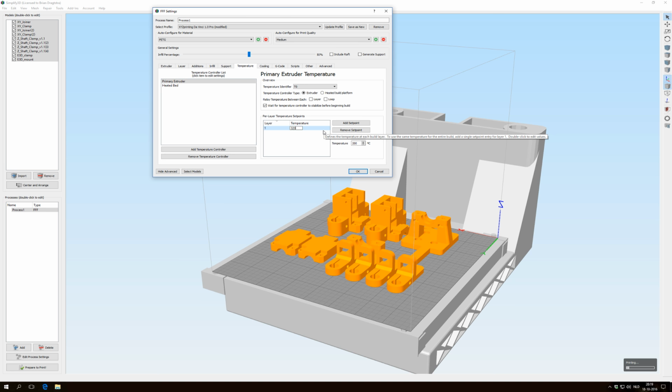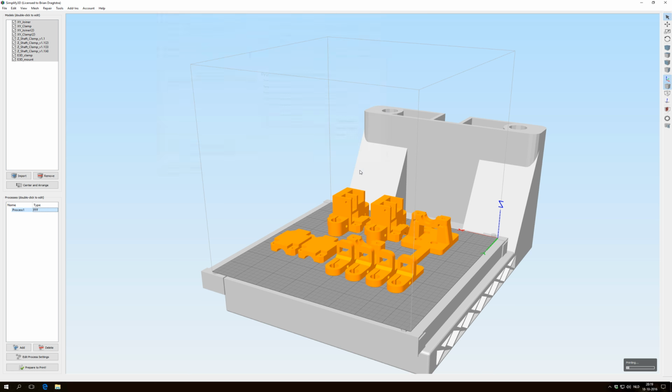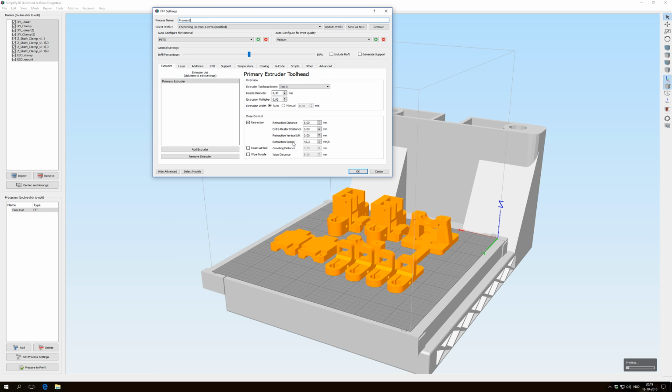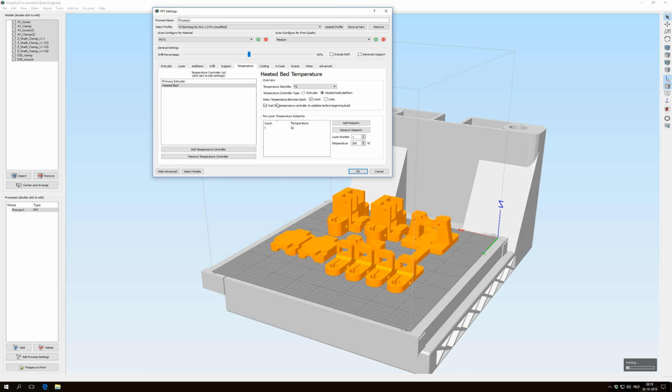So if I want this to be 320 degrees, then now it's 320 degrees. And really, it starts heating up my printer as far as 320 degrees. So if I'm stupid enough to leave this here, then it will break my printer if I'm on a stock extruder. With a good extruder you can go that high, but with this stock extruder you can't go that high.